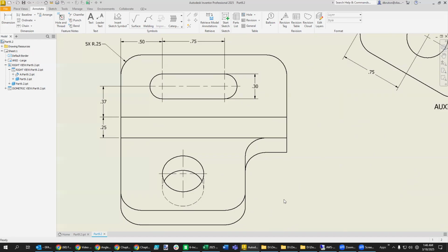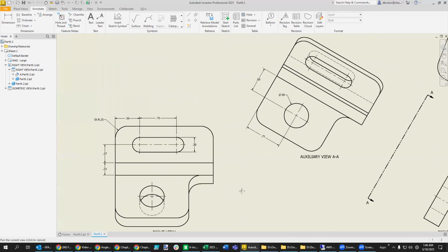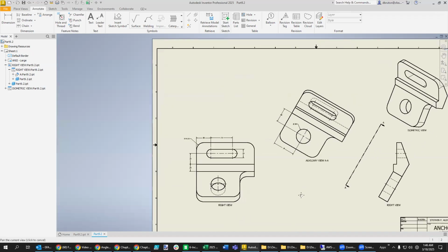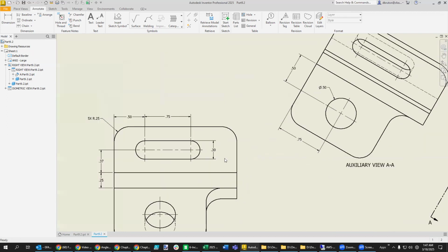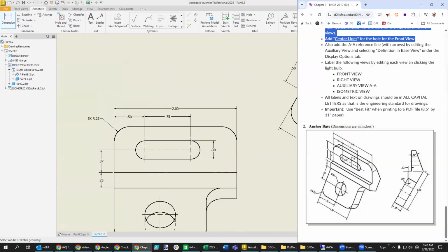All right, what else do we need on here? Do I have everything? How about the width of the part? Where would you put the width of the part? You could do it over here. But it looks like this one is flat up against the back, so it kind of makes sense to go back and go from edge to edge and just have this hovering above the other two along that axis. And that's how it is also in the view that we see right here.